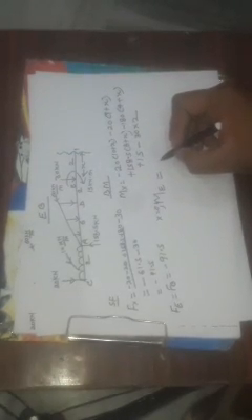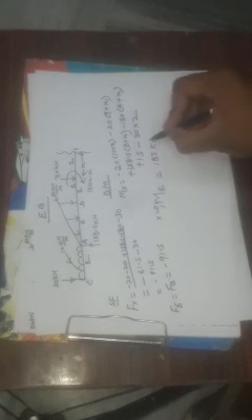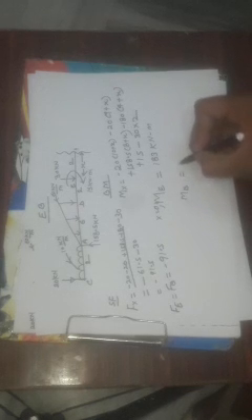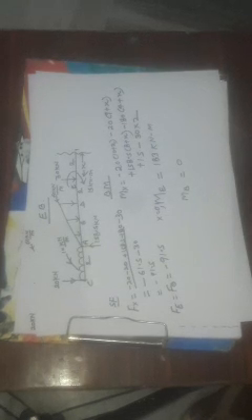Put the value of x as 0 here, then the value will be 183 kilonewton meter, and for point B it will be 0, as already discussed. For the start and end point of a beam, the bending moment value is always 0 until and unless an external moment is given. If an external moment is not given, then at both points the bending moment value will be 0.